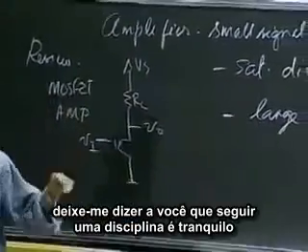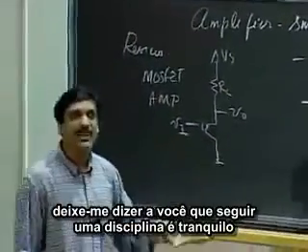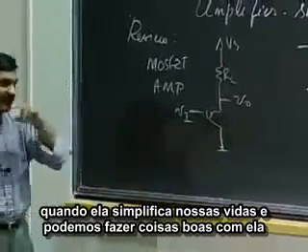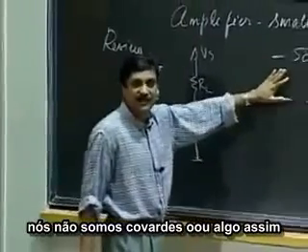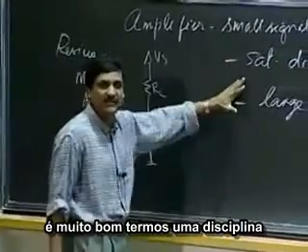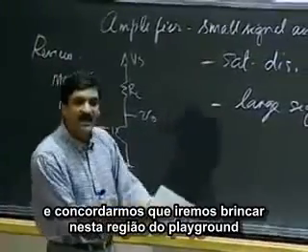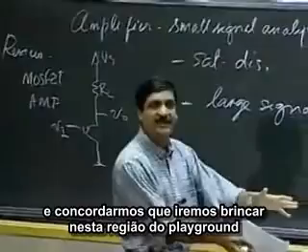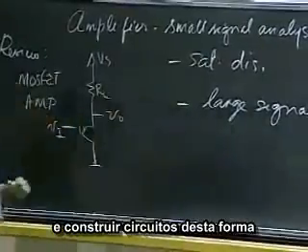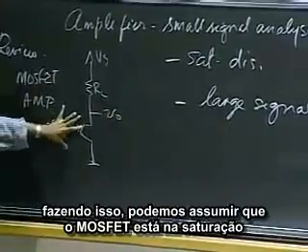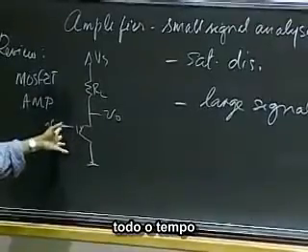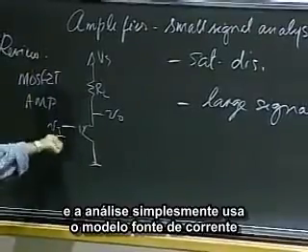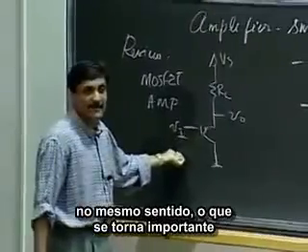Okay, and let me tell you that following a discipline is quite okay. Okay, when it simplifies our lives and we can do good things with it, it's quite okay to do that. Okay, we're not wimps or anything like that. It's quite okay to have a discipline and agree that we're going to play in this region of the playground and build circuits in that manner. So by doing so, we could assume the MOSFET was in saturation all the time. And analysis simply used a current source model.